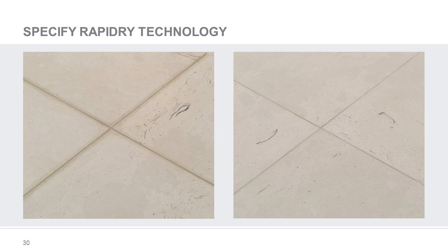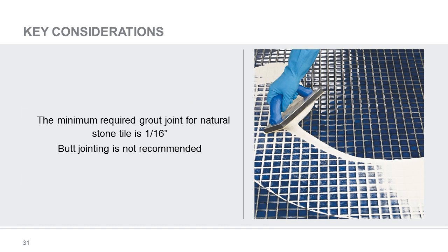Stone tiles should be carefully checked for grout retention on the surface, especially if a pigmented or contrasting colored grout is used. It's advisable to trowel a small area to begin with. Some natural stones will require sealing prior to grouting. In some cases, applying the grout to the whole surface of the stone tile can result in a more uniform appearance.